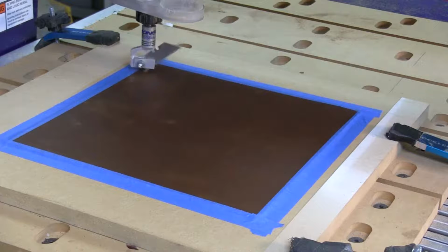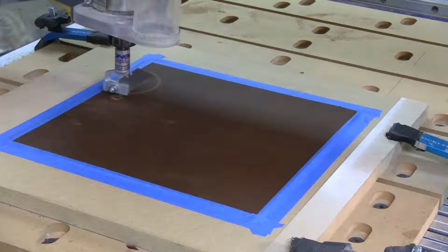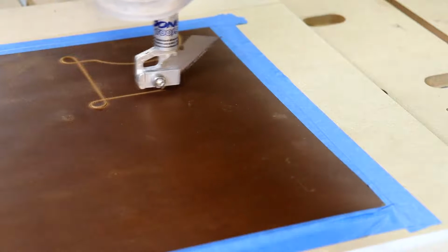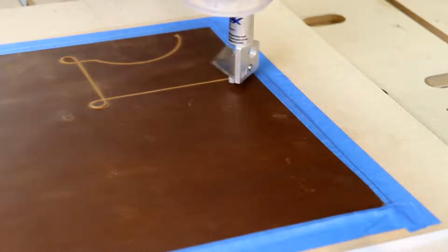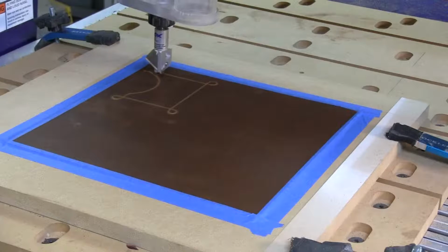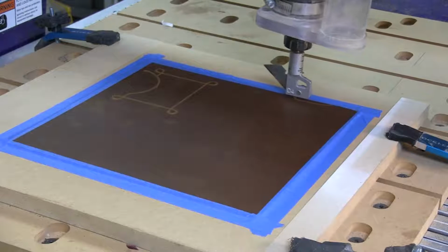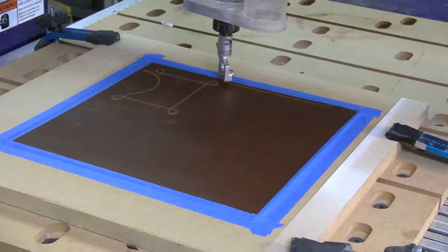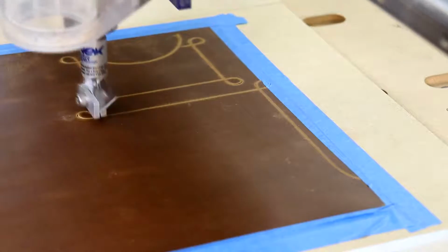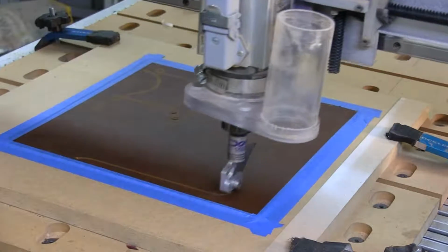Watch the drag knife enter the workspace, and as it gets to that first sharp outside corner, it takes advantage of the drag knife fillet that we added to the toolpath. That fillet provides such a simple way to get sharp outside corners on your leather projects. As the drag knife comes into the next component, watch for the lead right there. And then again, we're back to turning corners with those fillets. In real time, we're cutting at 100 inches per minute, but I've sped up the video just to move things along a little bit for us.